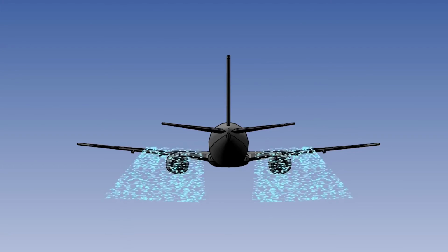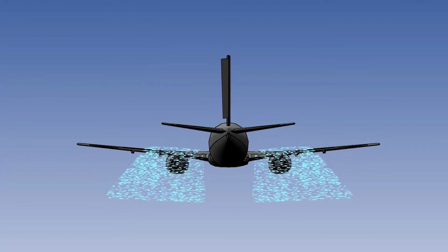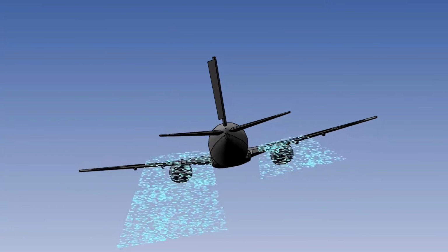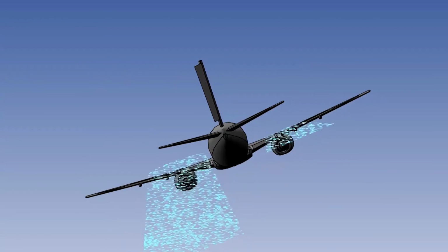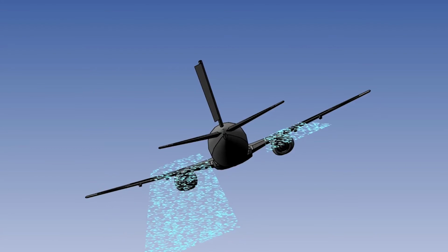The rudder should be used with great caution at any time when stalled or close to the stall, because of the possibility of causing a spin, on which more later. It is safer to use the rudder only after the wings are unstalled, and then only to prevent further yaw if a wing has dropped because it has stalled slightly before the other. It is generally safer only to use the ailerons to level the wings, also once the wings are unstalled.